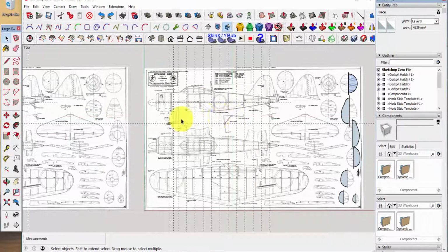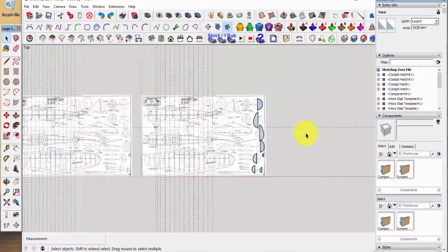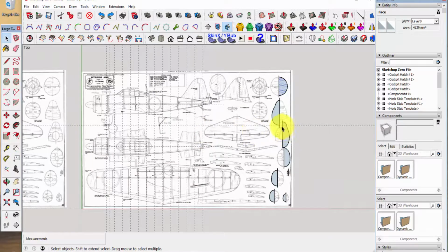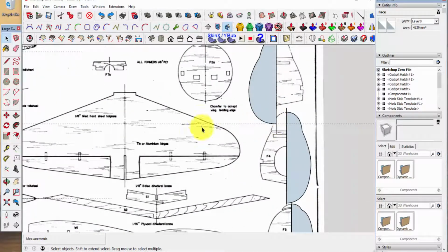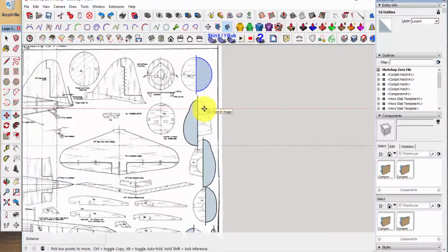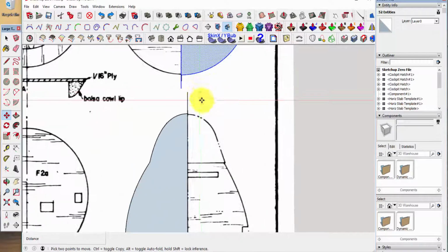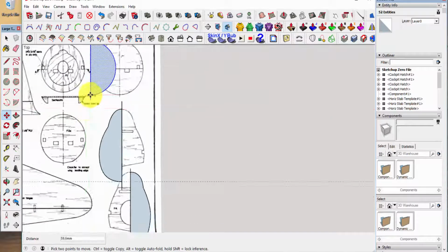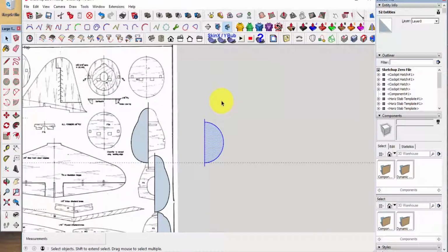Okay, so as I said, we're going to take these and move them down to a known good line. We're going to use this one down here that we used, as a matter of fact, to bring down our 30 millimeter distance. So now I'll take the copy, or not a copy. What I'm going to do is move the whole thing. Select it, select M for move, and for a reference, we'll just use the bottom of all of these. We'll move it down here and just drop it on that line. We know that that's on the ground plane line.